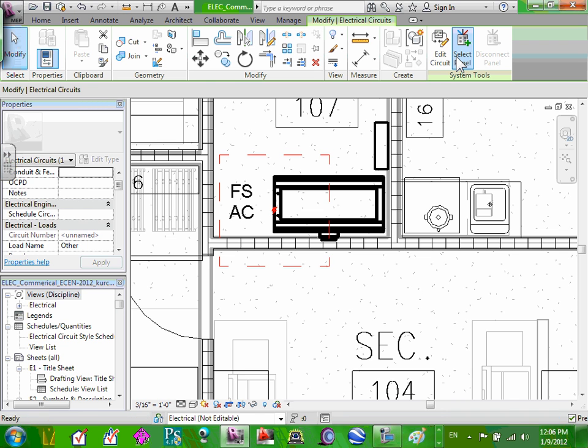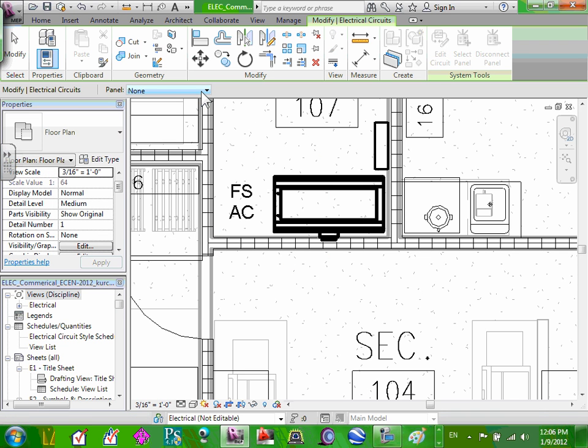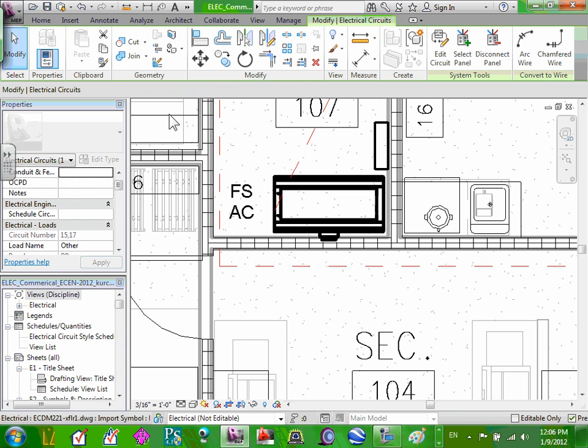Okay, now we need to assign a panel. Now where's this coming from? File server, division to provide disconnect, file server, total unit, full load amp, blah, blah, blah, located in the ceiling. It doesn't tell us anywhere, so I'm going to power this file server directly from the receptacle panel. So select the panel. Here's my receptacle panel. Okay, I circuit it from receptacle panel.